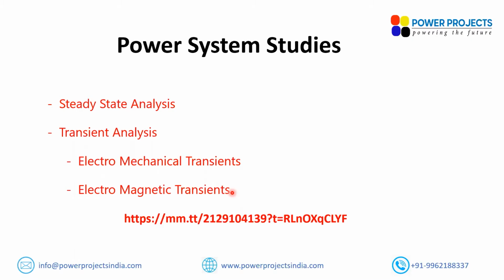When I'm studying, suddenly the generator load is disconnected. What's the rise in frequency? If you want to check that, I need not run the simulation with a microsecond or nanosecond time step. If I am running with a few milliseconds, that's good enough.